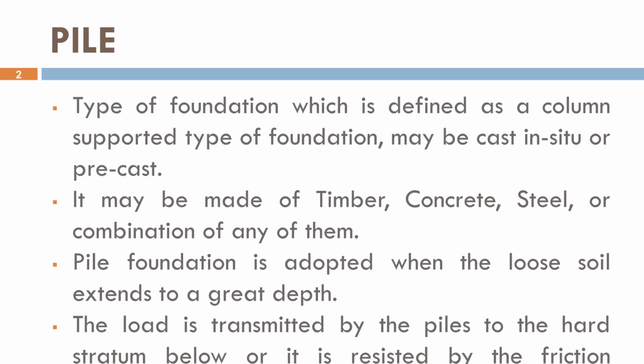techniques. A pile is a long, slender structural member that transfers loads from a structure to deeper, stronger soil layers or rock. Piles may be precast or cast in situ. Depending on project requirements, they can be made of timber, reinforced concrete, steel, or composite materials. Pile foundations are generally adopted when the loose or compressible soil extends to a great depth and shallow foundations become unsuitable. The load from the structure is transferred either through the tip of the pile, known as end-bearing action, or through skin friction developed along the sides of the pile. Sometimes, both mechanisms work together to support the load.